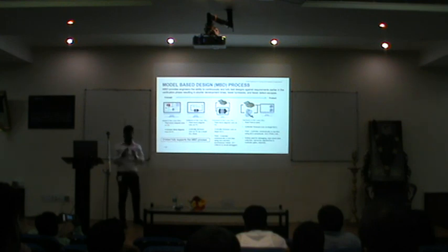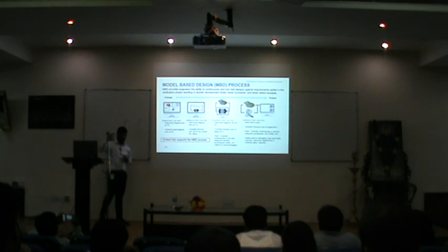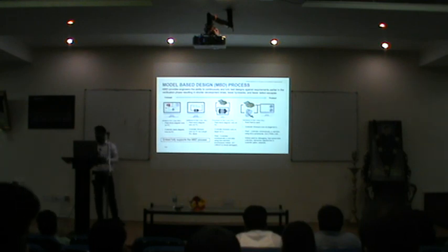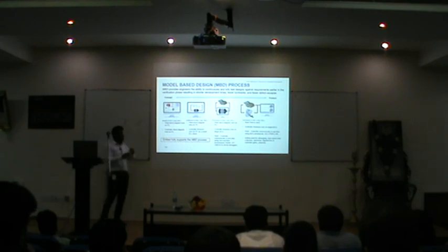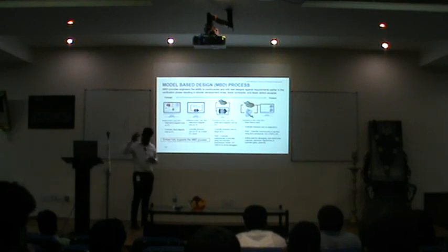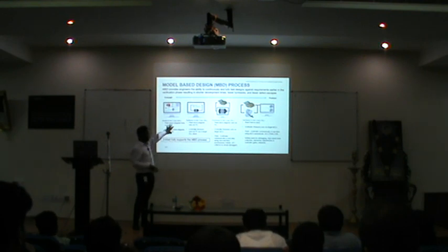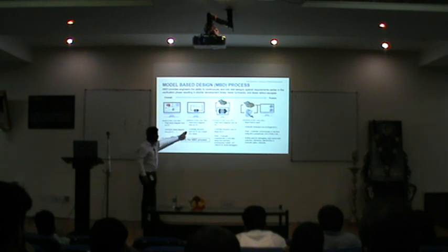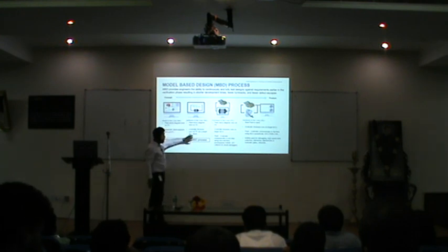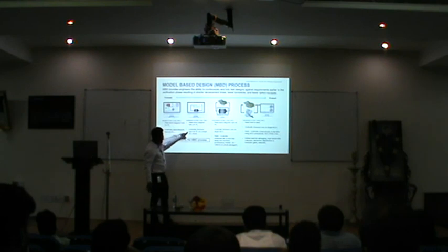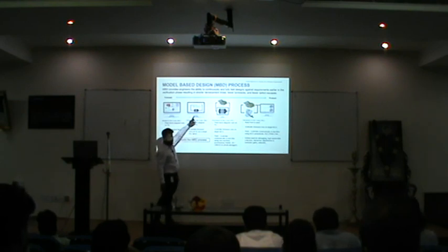When I say model in loop, it means we represent the motor as a virtual model, as a mathematical model, maybe as a state space equation or maybe as transfer functions. We can represent the motor, the controller with the feedback sensors, and the on-off switch. So everything is virtual; that is MIL, model in loop. Software in loop: you will have a DLL block as code. The controller firmware will be running as a DLL block, dynamic link library, but the plant will be a virtual model.